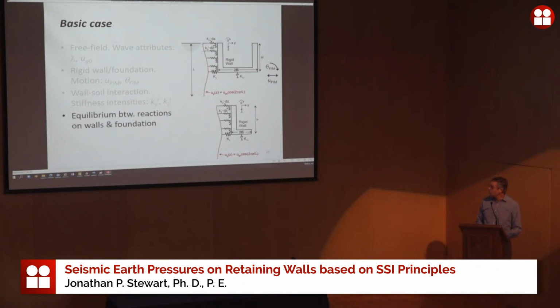Okay, so what we're doing to solve this is, for a given displacement here, we're going to get some deflections of the springs. These spring forces produce shear and moment, and that shear and moment has to be balanced by the shear from the base spring and the moment from this rotational spring. And so you can set up a series of equations for the horizontal and the rotational vibrations, and you can use those to solve for the foundation input motion and the theta, and this solution is for one frequency, and then you can work it through for all the other frequencies.